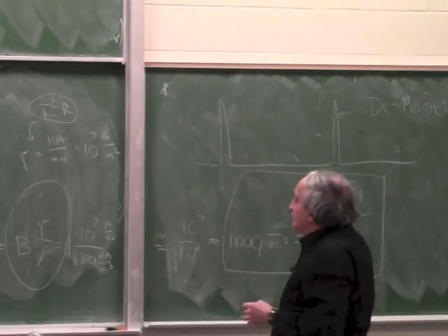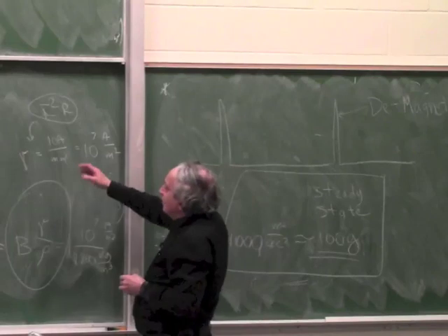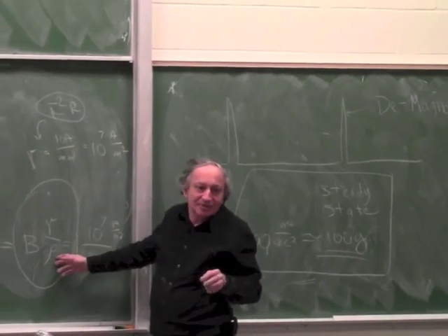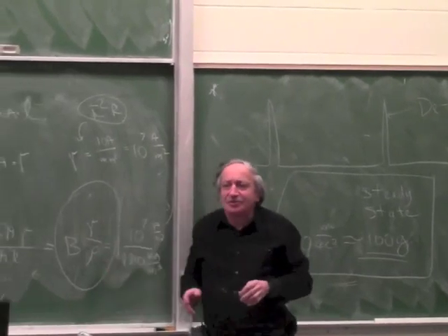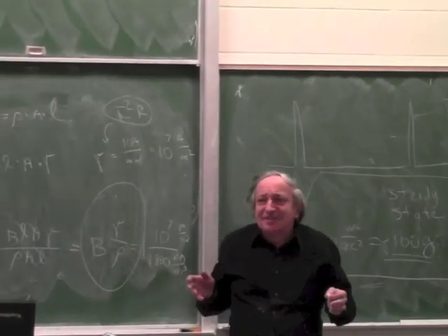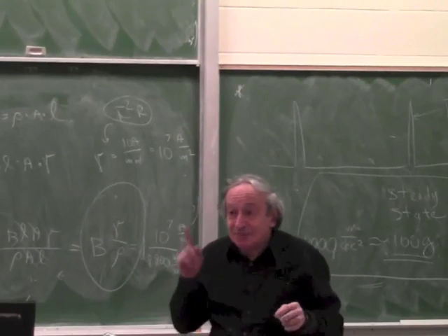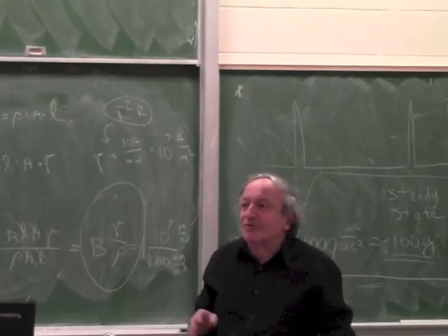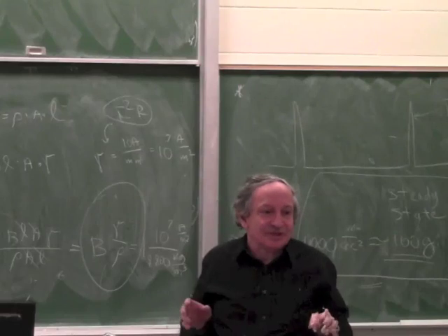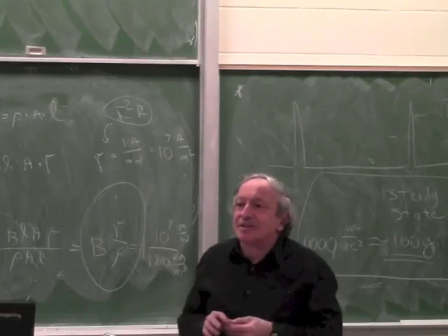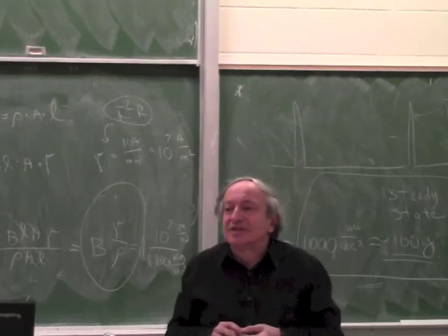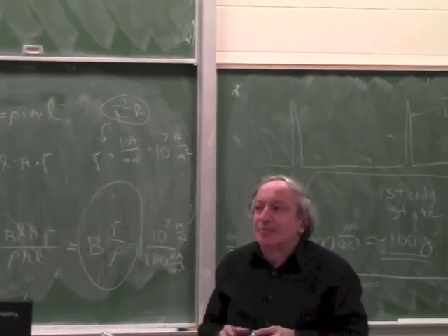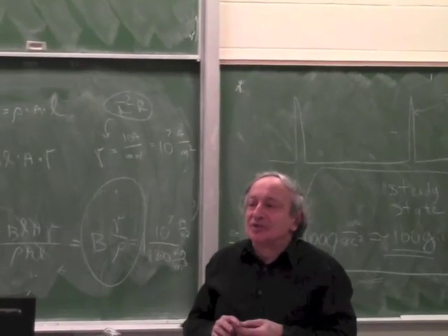Okay, so we can go to silver, but we only gain 10%. The density of silver is about the same as copper. So we can gain 10% going to silver, but it's a lot of trouble. It has been done though. At times where you need the utmost performance, you make the coils from silver. The most classic example is cyclotron coils and the coils of the isotope separators in the World War II Los Alamos